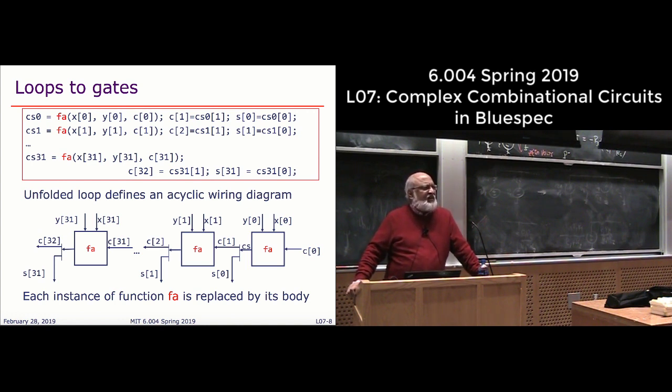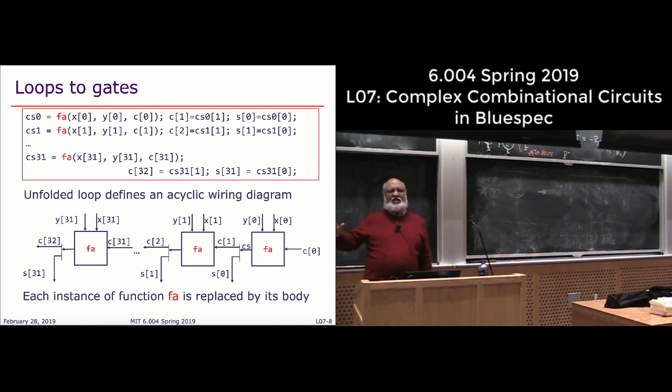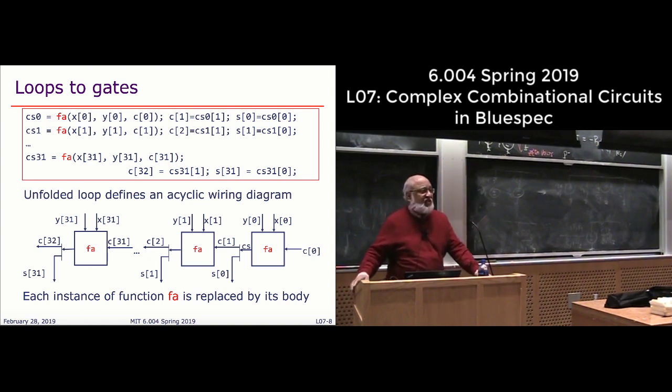How do you know that? I mean, I can just give you a pictorial representation of this. So you had a full adder, right? That's what you generated in the first cycle. And then you have the next full adder, and they're all being connected to each other. So assuming that full adder had no cycles in it, what we have generated here is also an acyclic interconnection of gates. And once we have done this, we can go and substitute whatever full adder looked like.